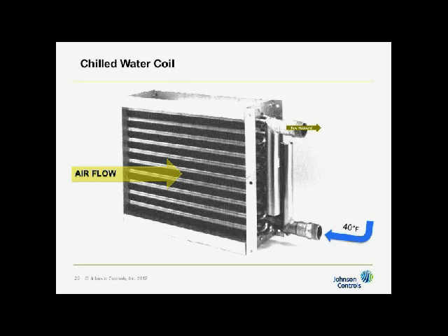But when I'm at dirty coil, then I have to pump more water through it to get the same work out of the coil. Even though the load hasn't changed, the work through the coil has. It just can't do as much without more water, so we increase the flow. And if you recall from my formula earlier on, load is equal to flow times delta T everywhere. So if my load hasn't changed on the coil, then my flow has gone up. My delta T has to come down.